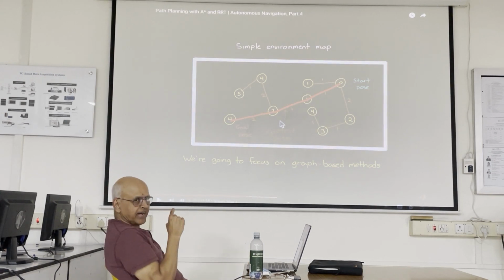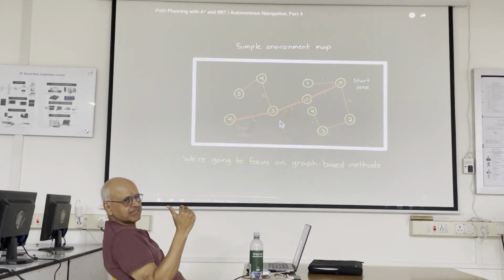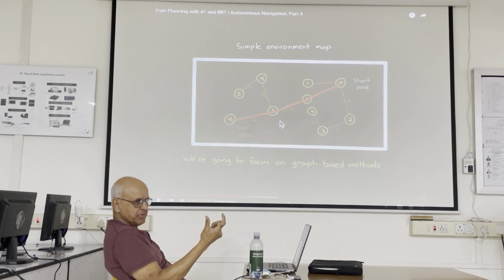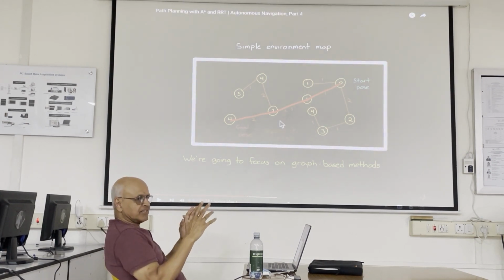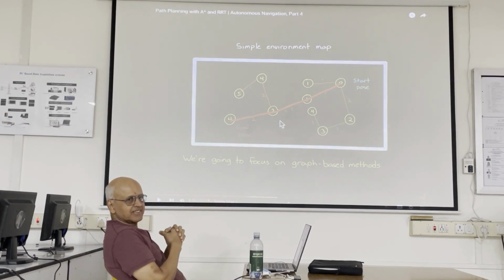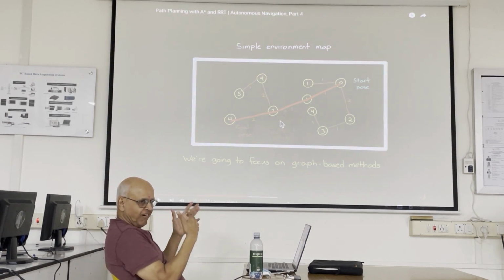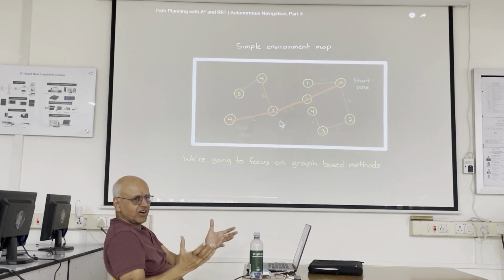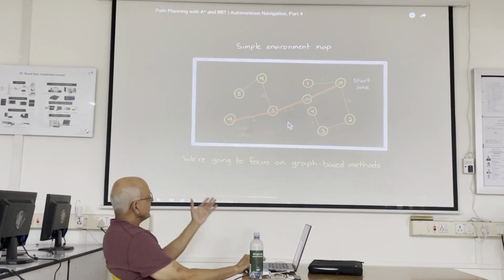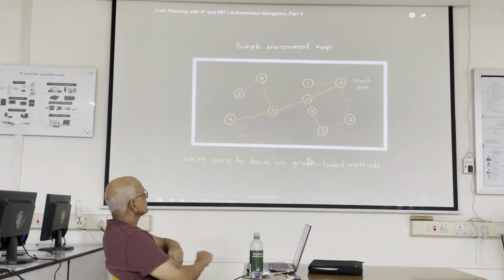So what he has described is the basis of the RRT method, the sampling based method. Yeah, but he's making an argument. He's not saying that RRT is useless, right? But he's saying that if you don't have enough samples, you end up with a suboptimal result. And so why not do it with A-star? Or if you want to use RRT, use a lot of samples. So it's kind of nice. He's got both covered, the random methods as well as the deterministic methods. They provide more efficient ways to build this tree.